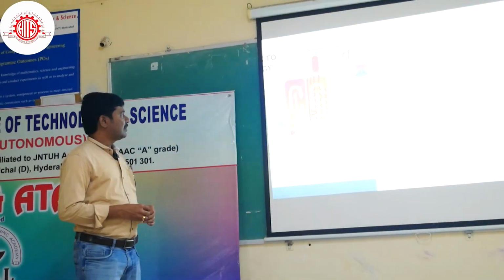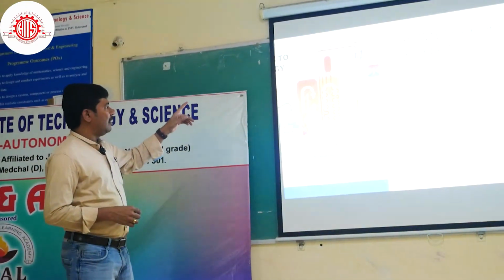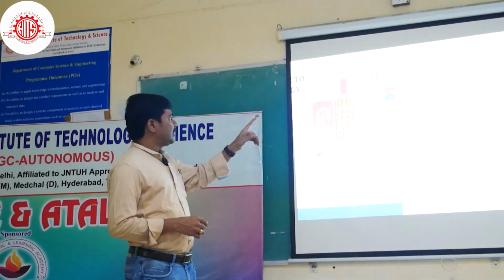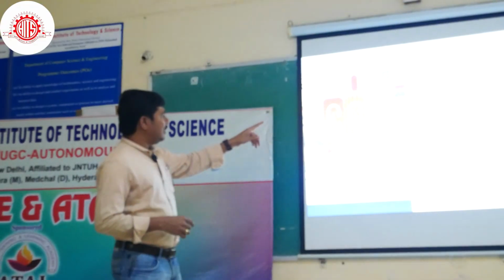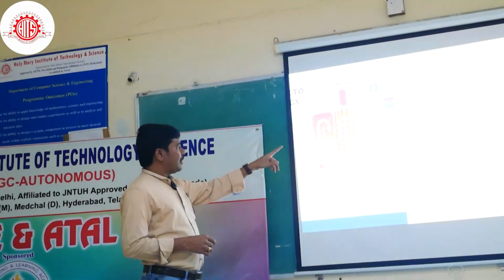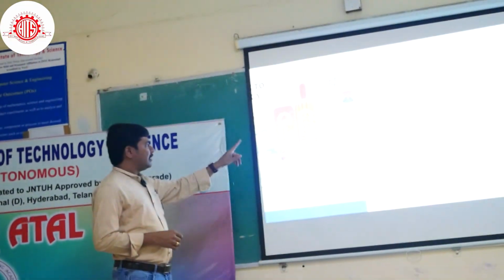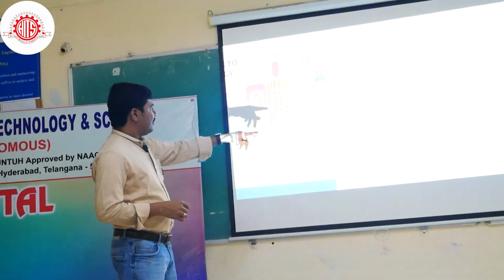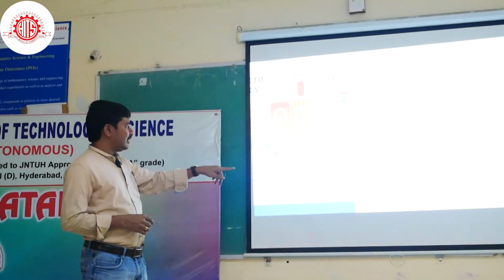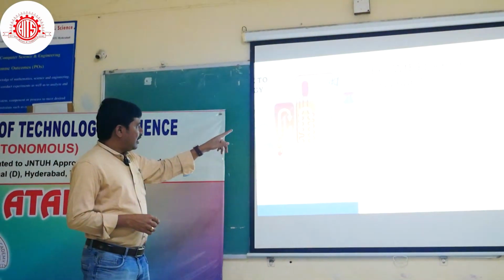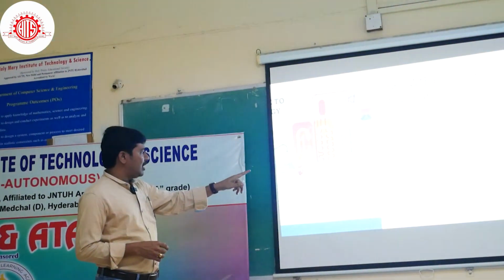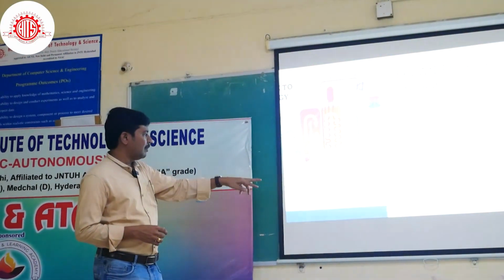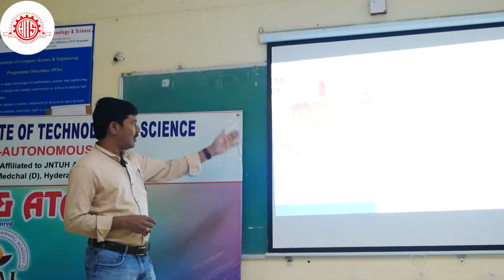Next. So this is the waste to energy process explained. Incineration is a thermal process, and like I told earlier, there is also a biological process. In this method it is clearly identified that this thermal process reduces waste volume by up to 90%, and requires a flue gas cleaning system, and modern plants include energy recovery. This is one of the methods.